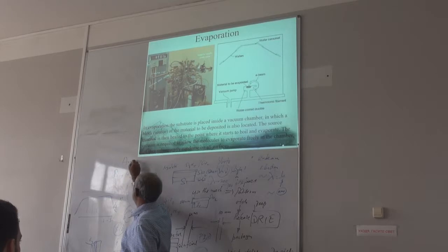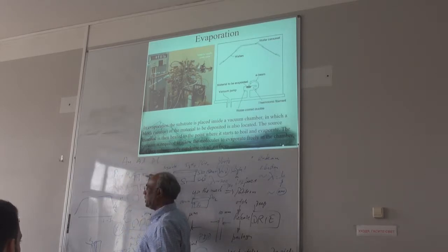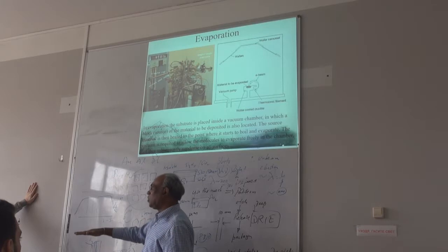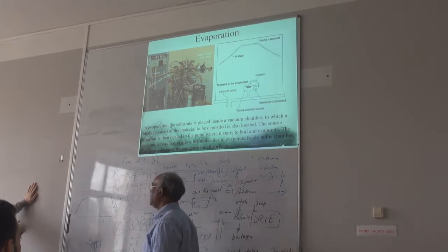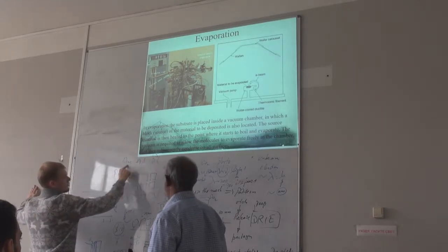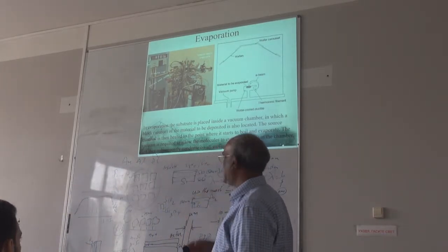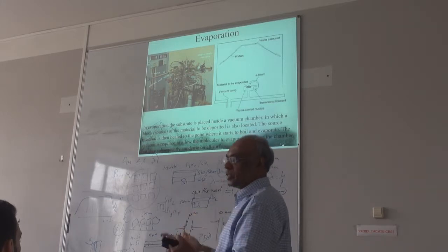Sometimes we use chromium: if the gold doesn't stick, first we put a chromium layer, then put the gold. So chrome and gold, it all involves metal deposition.